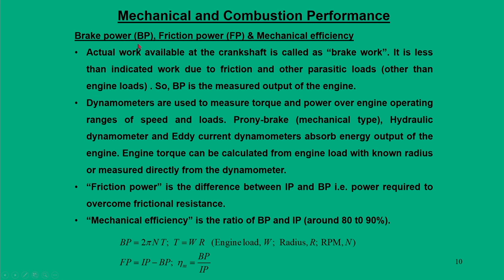So, these two terms go side by side, and the last term is the mechanical efficiency, which is nothing but the correlation between the brake power and the indicated power. Now, let us see in what way we are going to get the estimates of brake power and friction power.